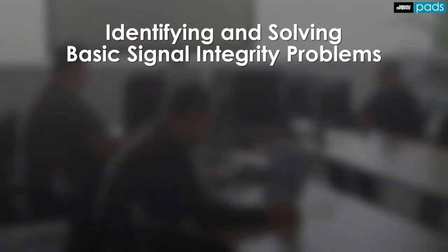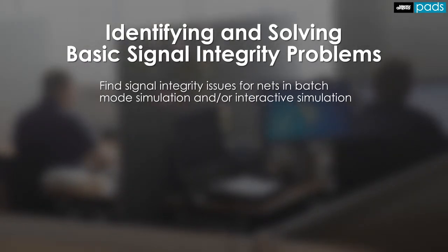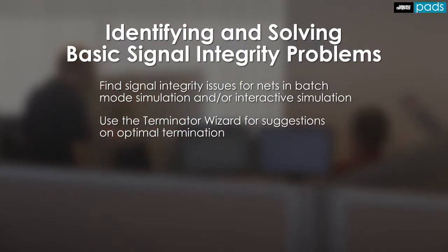Signal integrity problems on the PCB can easily be located and fixed using HyperLynx. After exporting your design, you can run simulations either in batch mode or interactive mode to identify any potential signal integrity issues. The built-in Terminator wizard can analyze the topology and suggest the optimal termination.